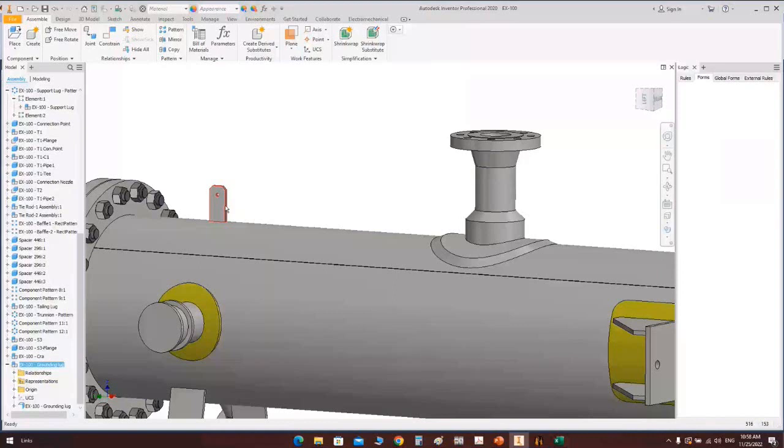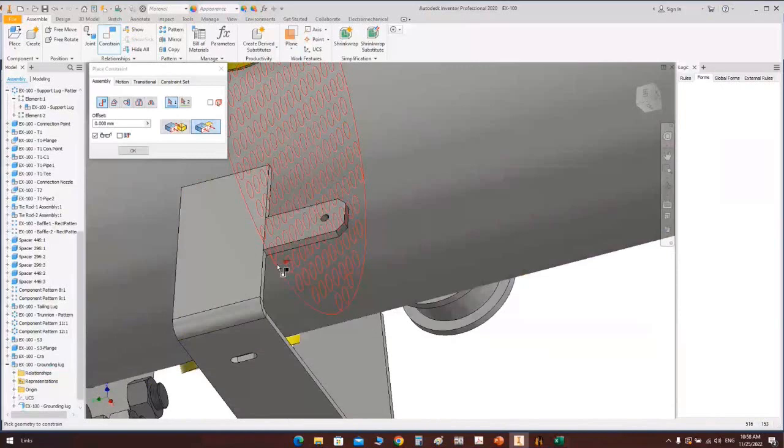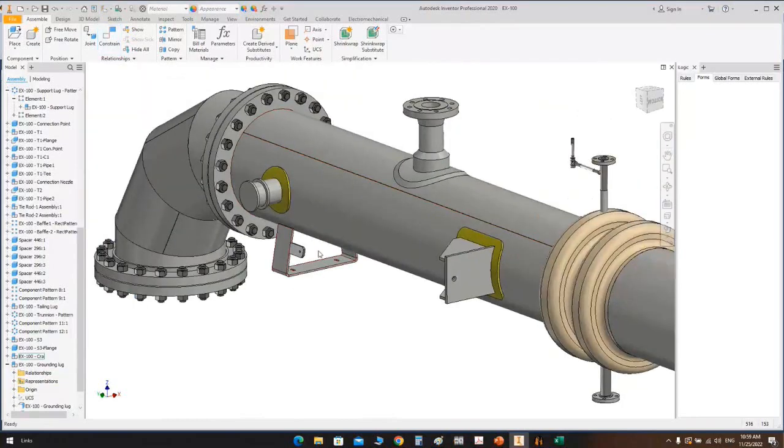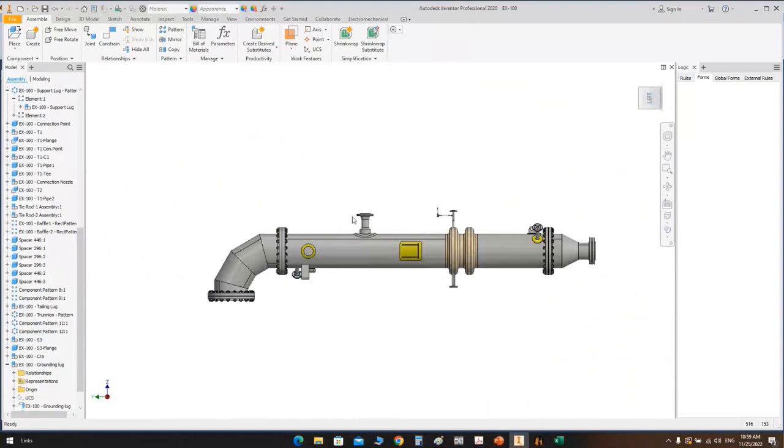like that. Make that surface parallel to that one, and make that one offset from the base with, let's say, 20 millimeters, 100 millimeters. So that way you can do that, and the earthing lug will appear on the bill of material because it's included in the library.